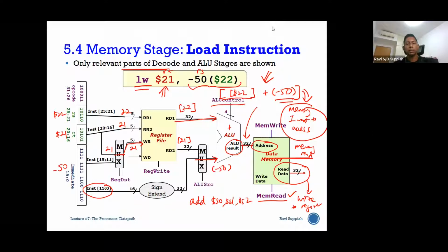The multiplexer is hardware we introduced to you here because it is needed for you to understand how we are able to select between different inputs and choose just one of them to be channeled to the next stage. The reason we have all this is because we want to keep the processor design as simple as possible by reusing as much of the blocks as we can.